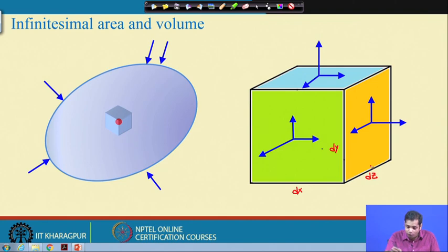And then we have normal stress, this is normal stress. Since it is now 3D, going back to the previous example, when we have a load in a 3D direction, we have one normal stress and 2 shear stresses; these are all shear stresses. On all these 6 planes, we can have normal stresses and shear stresses.